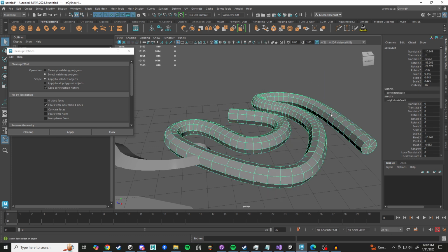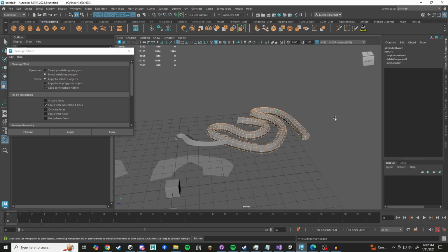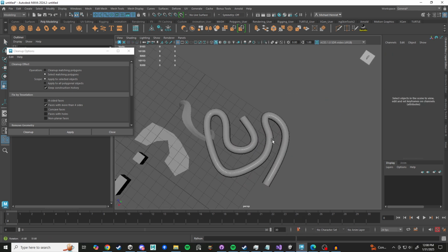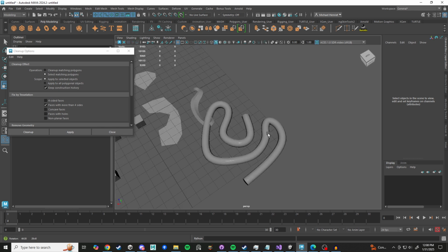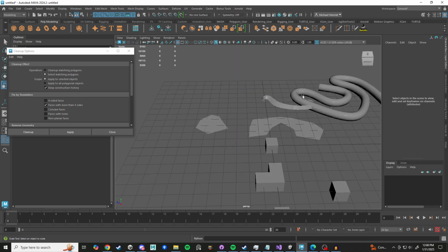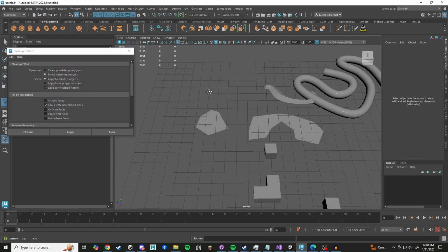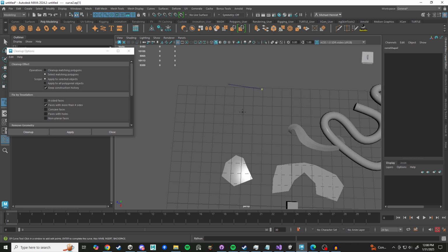And then after the fact, we can go into face mode or edge mode and soften edges there. And then we get a nice smooth shaded shape right there. So that is extruding long curves. There's also, let's create another curve because there's an even better tool for this. I mean, not to say that that's a bad tool. You can definitely make any sort of extrusion shape and it'll be really useful there.